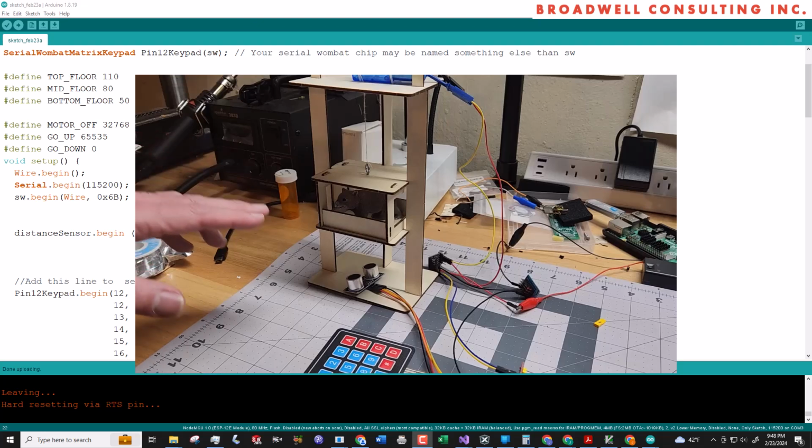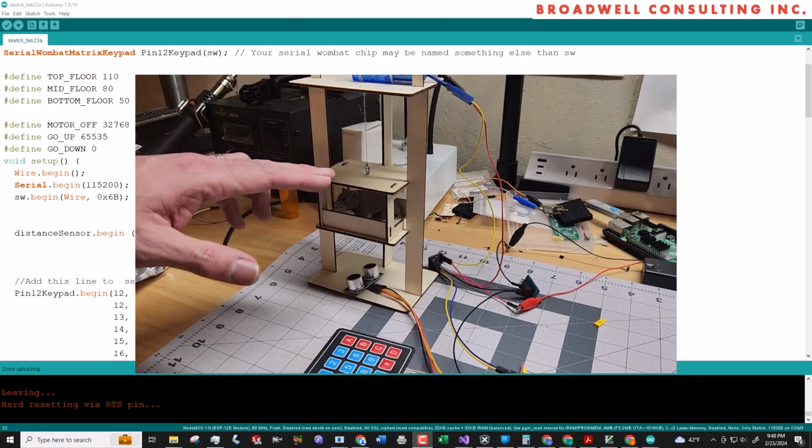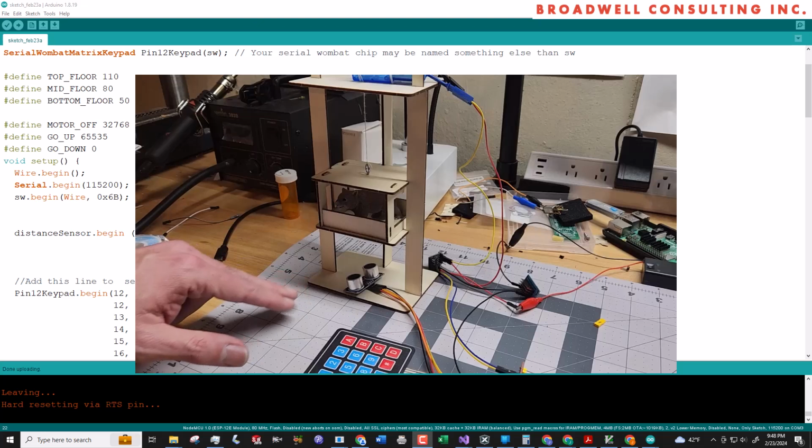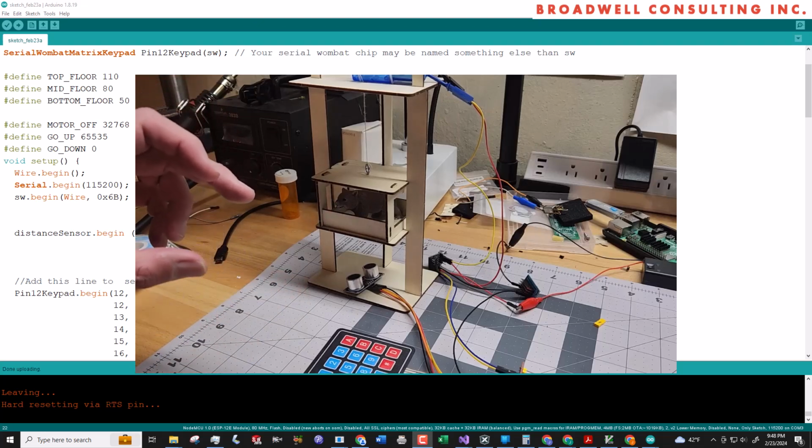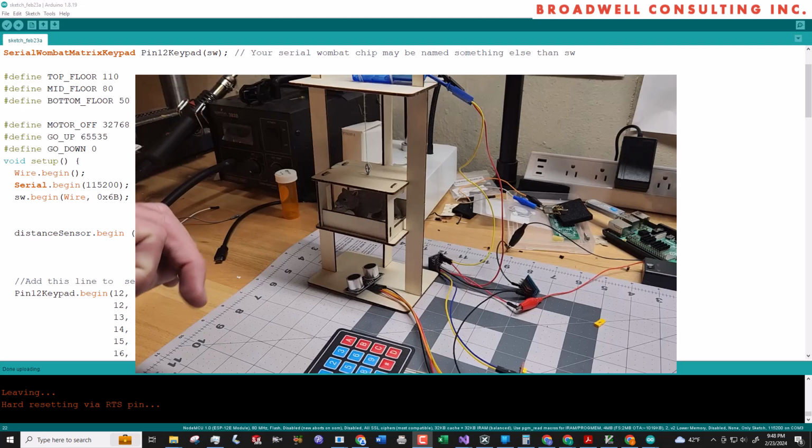And so it was not detecting the fact that the thing was moving and I was hitting the top of the elevator tower. So that's not good. So for small values, go with an average. For larger moving values, go with a filter. And this is especially true if you're using heavy filter constants.